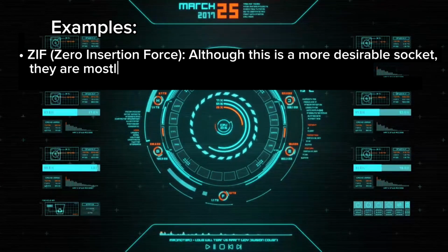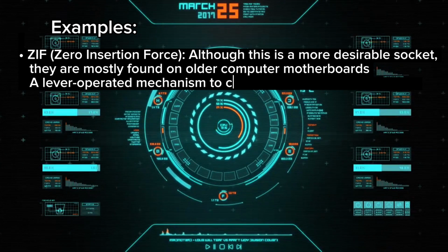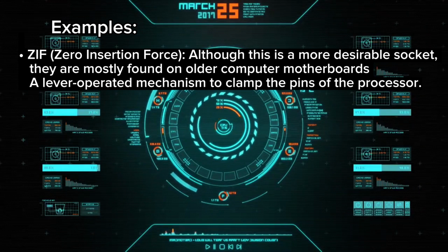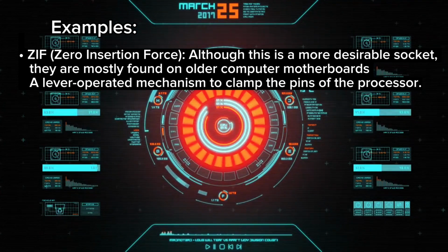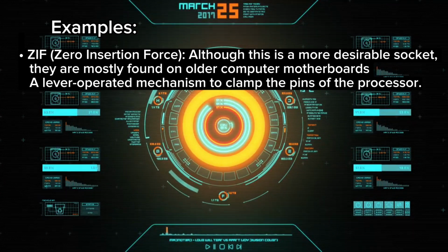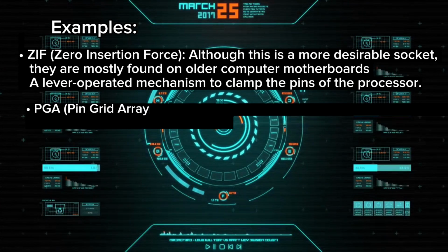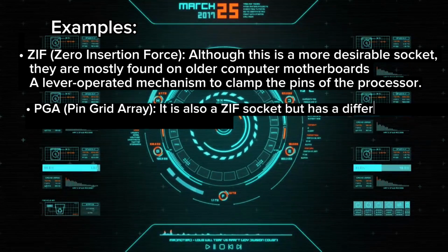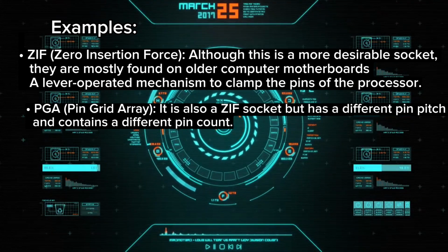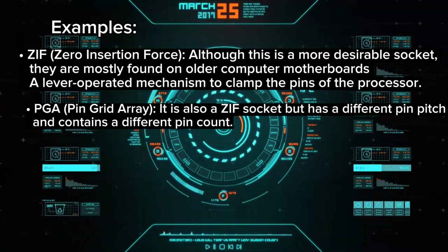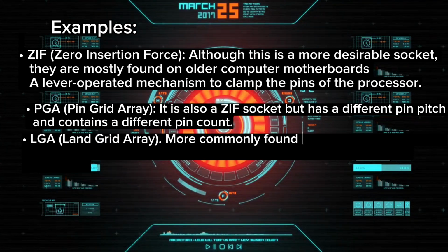ZIF, or Zero Insertion Force. Although this is a more desirable socket, they are mostly found on older computer motherboards, with a lever-operated mechanism to clamp the pins of the processor. PGA, or Pin Grid Array. It is also a ZIF socket but has a different pin pitch and contains a different pin count.